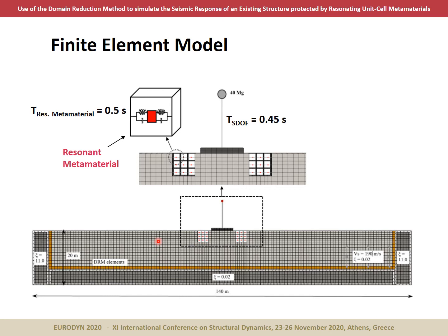this inner domain. So in this particular case, we generate some shear waves that propagate vertically, and when they interact with our system here in the middle, some radiated waves are generated that will eventually enter this outer domain. And the purpose of this domain is to damp out those radiated waves coming from the oscillation of our structure.